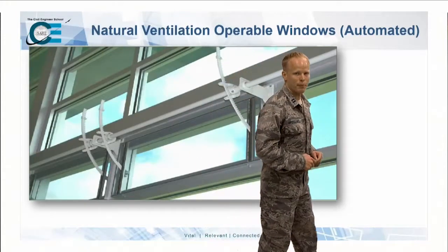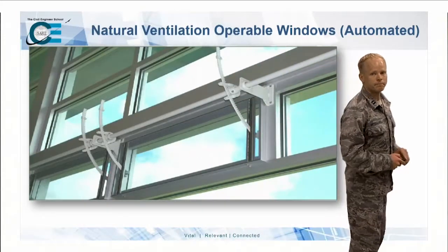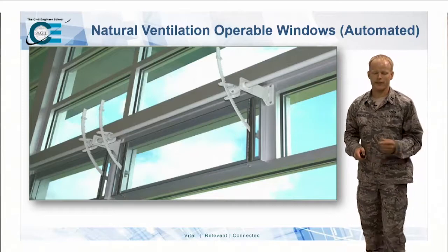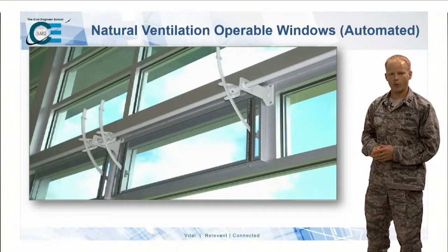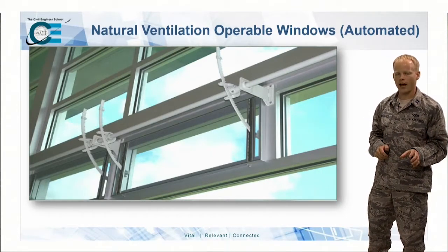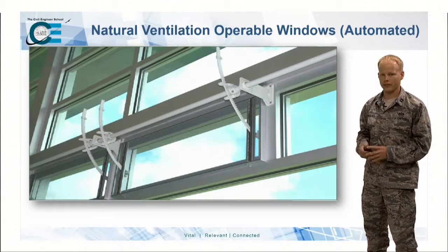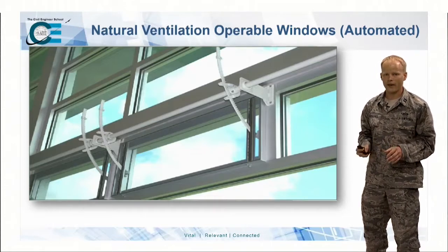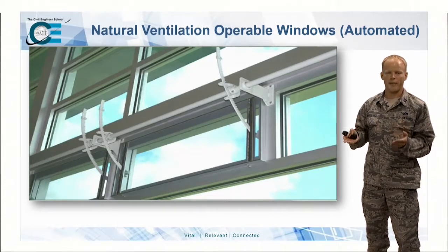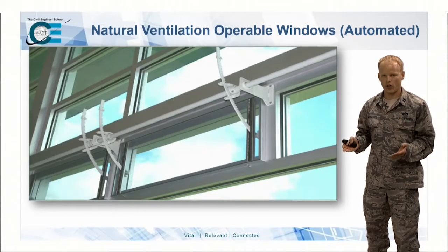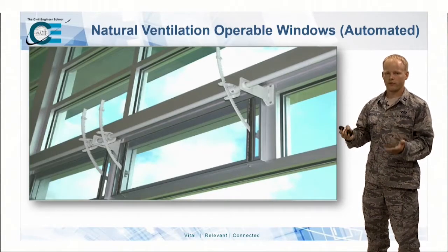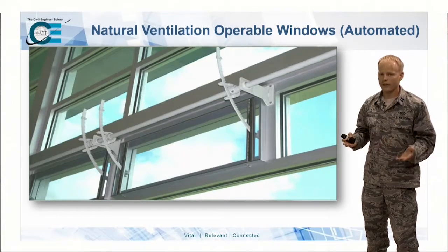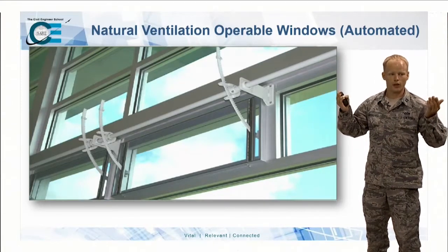Natural ventilation and operable windows. Last summer, I was working at NREL, and they had operable windows. So this works like an economizer, but directly for your spaces. When it was cool outside, these windows would automatically open and automatically close when there were no longer favorable conditions for natural ventilation. Or you just open the windows when you know it's cool outside.